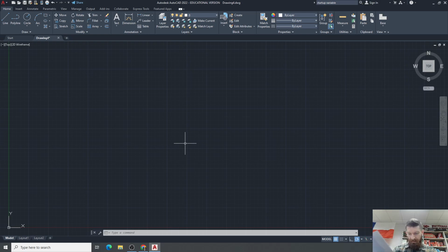When AutoCAD prompts for a point or a distance, you can respond by entering values at the keyboard. The values can be in any format: integer, decimal, fractional, or scientific, regardless of the format of the unit selected. You can type in explicit feet and inch values only if you're in the architectural or engineering units. So let's talk about that real quick, because that might be helpful.